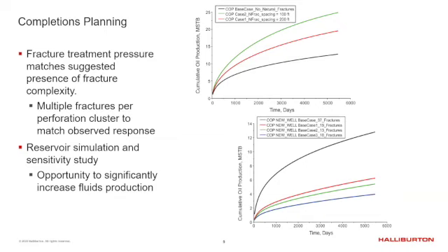So what it's telling you is that surface area really matters. That's kind of the thing here, right? And we'll come back to this in a little bit because it's telling me something else that we didn't really realize at the time. The bottom curve is really just the number of fractures. And if you look at the black one, 37 fractures, the next one's 19, 13, and 10. As the production goes down, this tells us more fractures better. More fractures are going to work better, which is now today kind of common knowledge in the industry. At the time, this was not. This was pretty new stuff at the time.